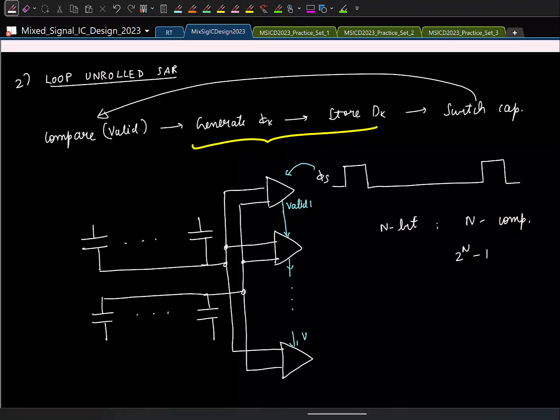I mean, let us say if there is no offset, right? If I were to plot the input-output characteristic of the ADC, how will it look? It will be an ideal staircase. So now if each comparator has a different offset, what will happen? Yeah, it will basically be distorted. It will introduce non-linearity. Okay. So now we can't tolerate any offsets in these comparators. So you have to go and correct for it. And as we discussed during the comparator time itself, this is usually done in the digital domain through some form of digital calibration. So this is something that you have to do here.